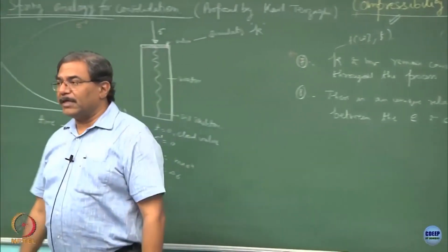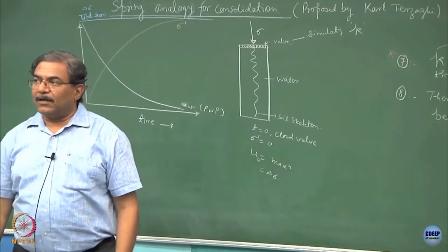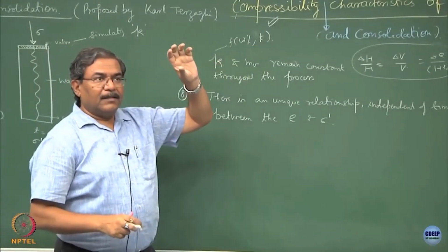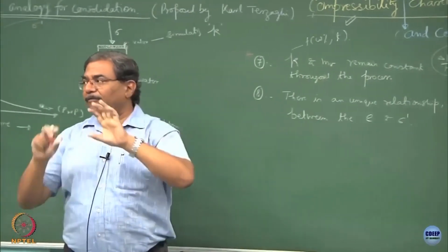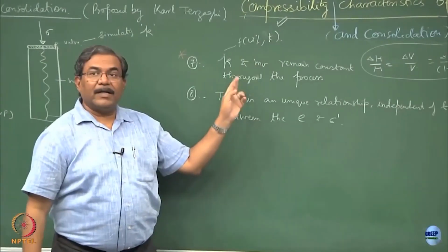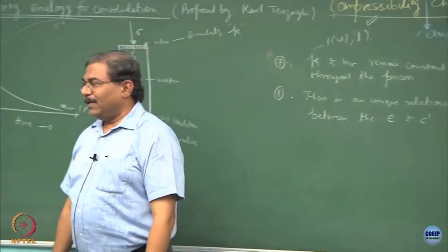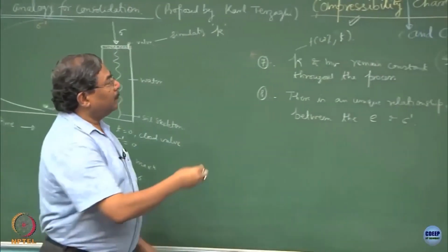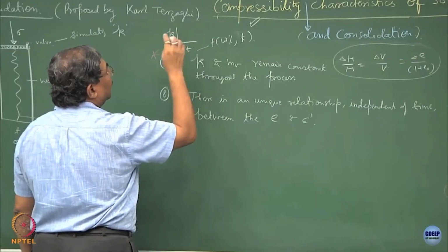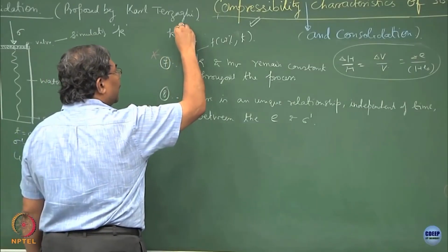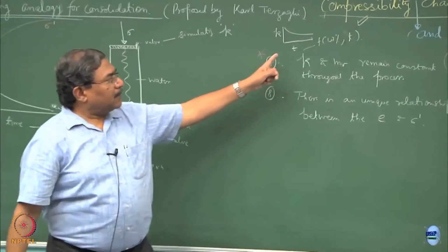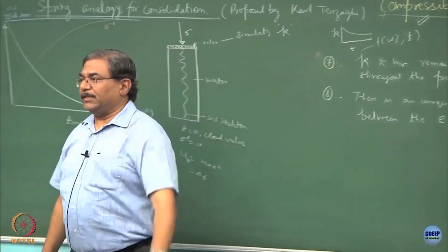When we were doing the constant head test, I think I had talked about this, that for a fixed time duration we take 3 readings for the drop of head. If time intervals are very high, then your hydraulic conductivity is bound to change. Otherwise also, if you plot K versus T, what you will observe is that hydraulic conductivity decreases with time, particularly when the times are of the order of months and years.